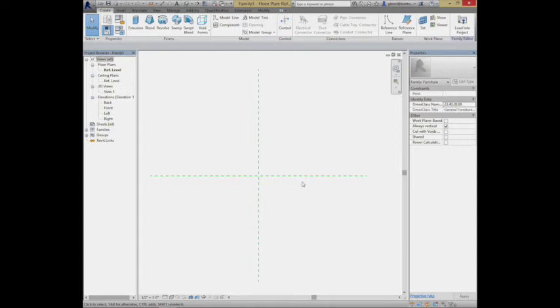And as we're drawing planes, here's what we're going to do. We're going to go to the reference plane tool, so over there in the datum section. Where is my mouse? Do I leave a mouse hanging around over here? I did leave a mouse, thank you. You could be mysteriously controlling things on the screen, freaking me out, and I would never know what's going on there. Okay, so we're going to go through and grab some reference planes.